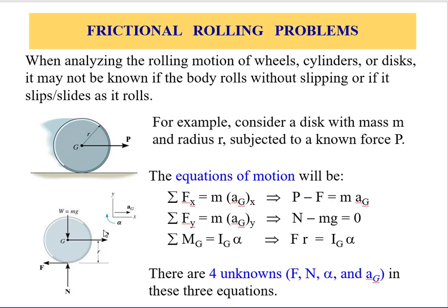Now, applying the free body diagram also needs a kinetic diagram. Typically, the kinetic diagram is chosen along the assumed direction of the inertias. There are two inertias here: rotational inertia, which in this example we assume counterclockwise to be positive, alpha, and a positive acceleration or deceleration of the center of gravity G to the right in the x direction. And also we have in the y direction aGy, but it's zero, we know by default.